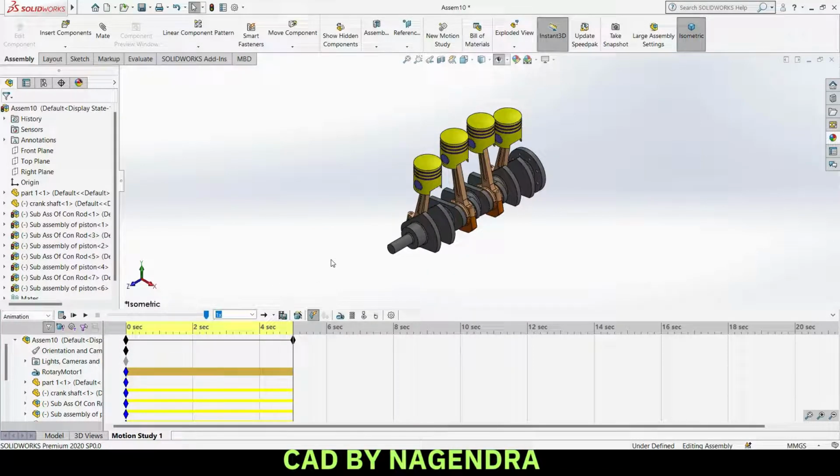Then next to that, we can increase or decrease the speed of that motion simulation. For example, I'll keep here 0.25, like slow. Then we are able to change different orientations here. Normal means only in one direction from starting to ending it will come. If you make it loop mode, the same step will be repeated again and again. Reciprocate means first it will go clockwise, next it will come in the anti-clockwise direction. Now for this one we will make it loop mode.